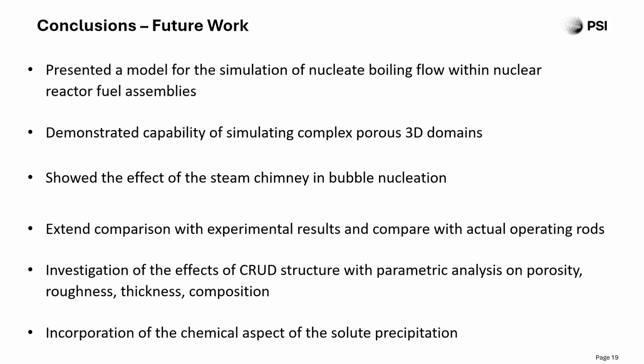For future work, of course, we want to extend the comparison with experimental results and compare with actual rods from the Swiss nuclear power plants. And obviously, the CRUD has a lot of aspects we want to investigate: its porosity, the roughness, the thickness, and the chemical composition. In fact, eventually we want to incorporate the chemical aspect of the precipitation itself, so look at the boiling while the precipitation is happening.